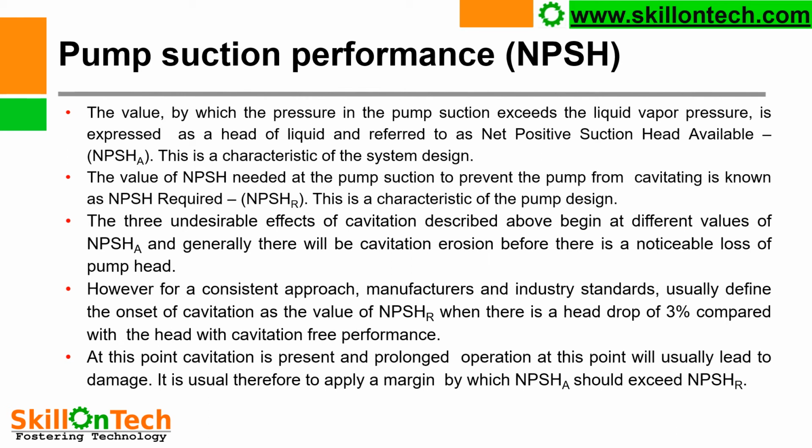The three undesirable effects of cavitation described above begin at different values of NPSH available, and generally there will be cavitation erosion before there is a noticeable loss of pump head. However, for a consistent approach, manufacturers and industry standards usually define the onset of cavitation as the value of NPSH-R when there is a head drop of 3% compared with the head with cavitation-free performance.